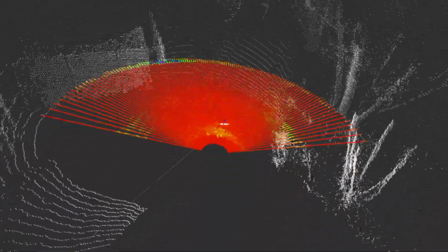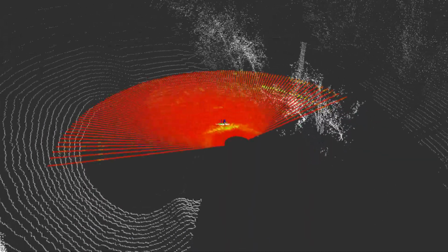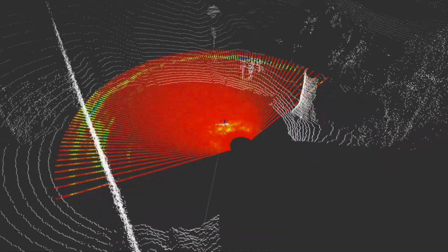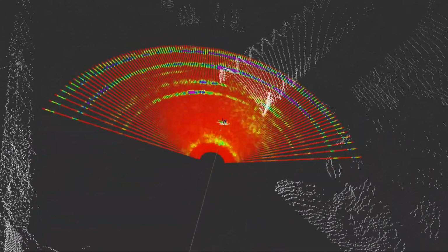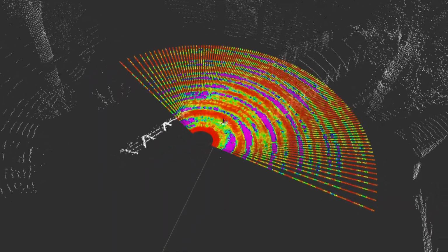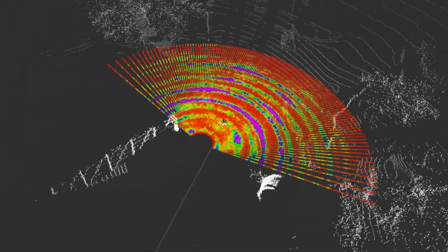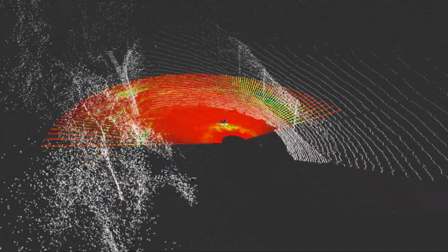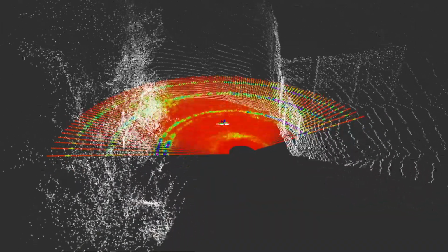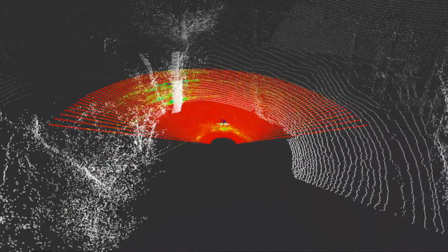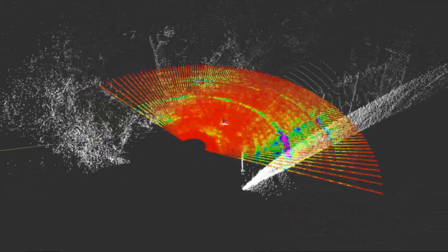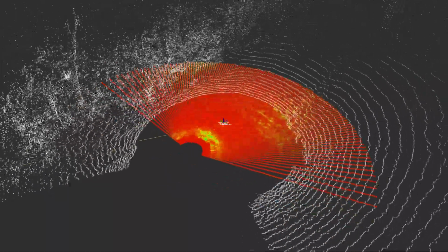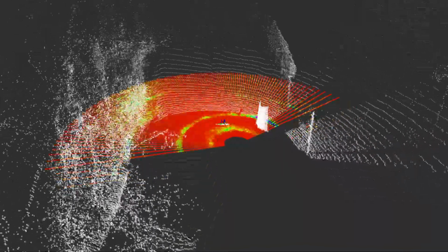I'd also like to highlight another advantage of the ColoRadar dataset over existing radar datasets. We include the raw data streams from our radar sensors. Now, existing radar datasets use the signal processing and target detection methods implemented on board their sensors. These methods are usually designed specifically for applications like advanced driver assistance and are ill-adapted for robotics work as a result. Our dataset provides raw, unprocessed ADC samples and dense 3D radar images for each radar measurement. This gives users the flexibility to experiment with new signal processing methods or to use our pre-processed radar images.